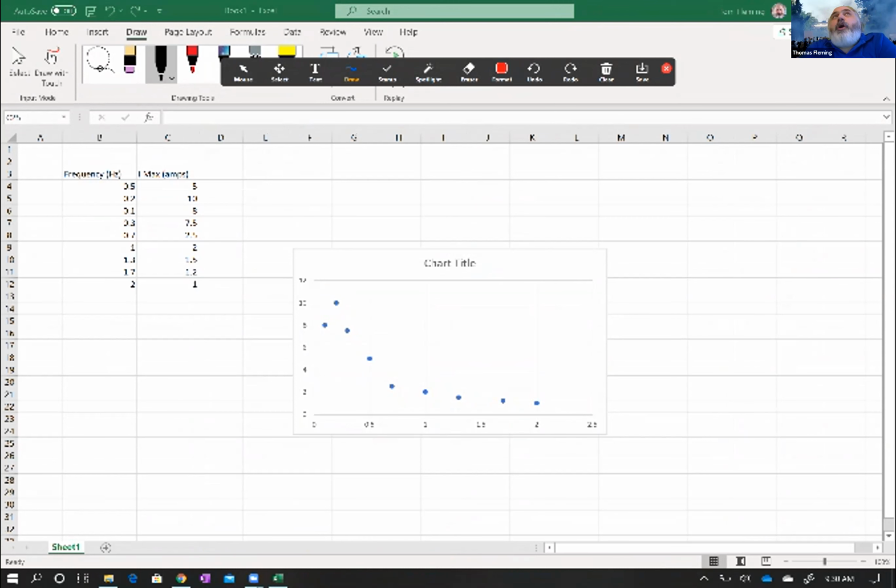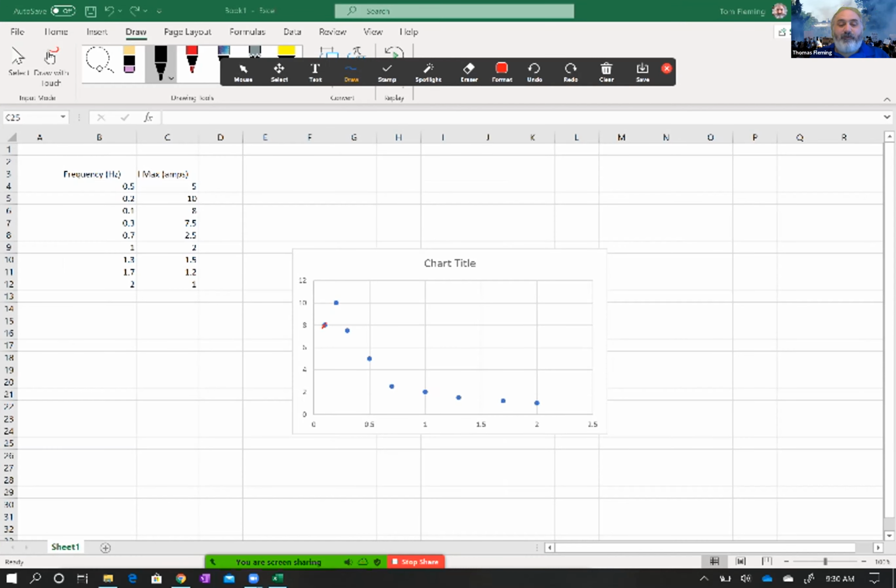We want to be able to show that there is a resonant frequency, and at that resonant frequency I get a very large current, but above or below that frequency I get a dip. And I was able to achieve that here. You can see I have a local maximum, but my graph is something complicated.